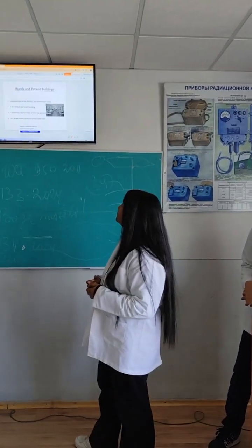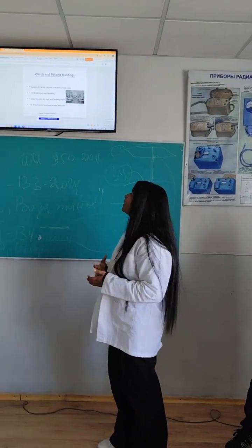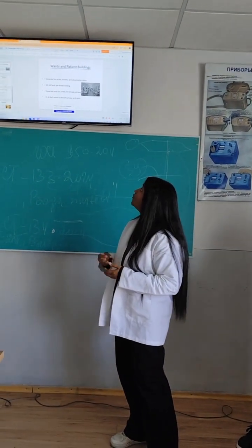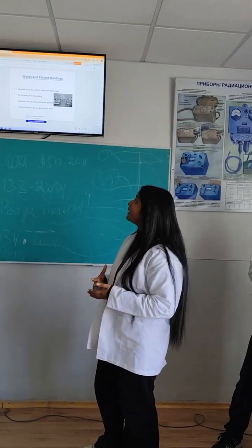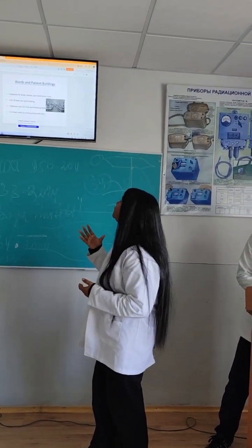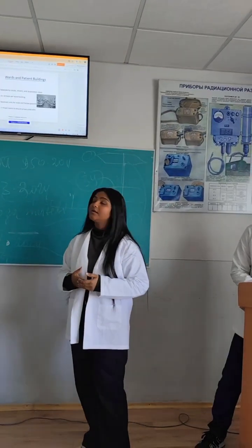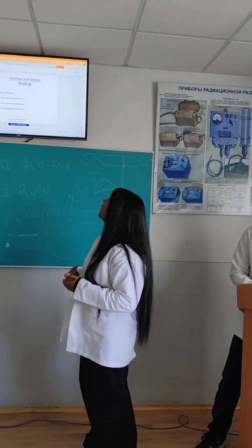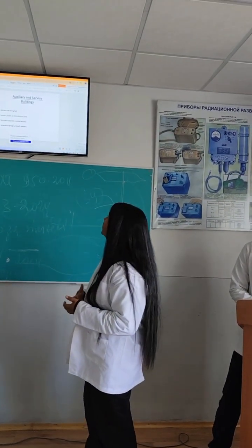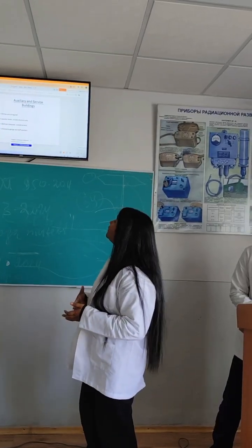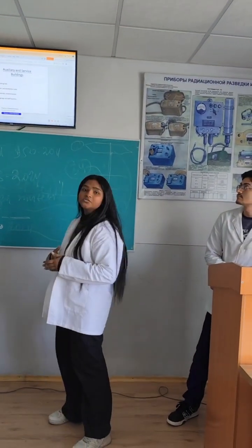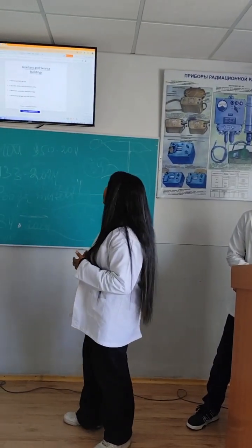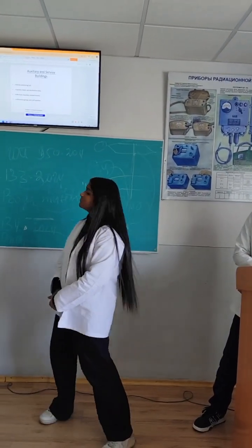Wards and patient building. Separate for acute, chronic and observation cases. 25 to 30 beds per ward building. Separate units for male and female patients. 1 to 4 beds to ensure privacy and calm. Auxiliary and service building: kitchen and dining hall, laundry, boiler and disinfection unit. Mortuary, with separate isolated access. Ambulance garage and staff quarters.